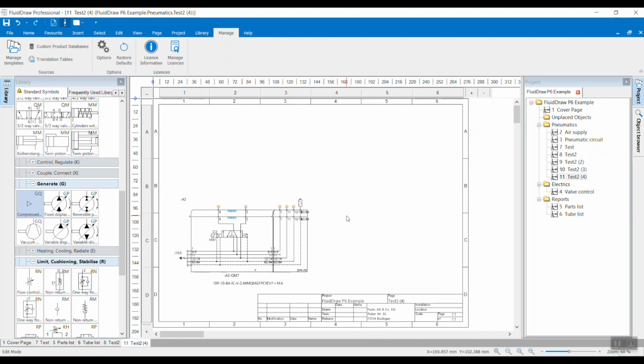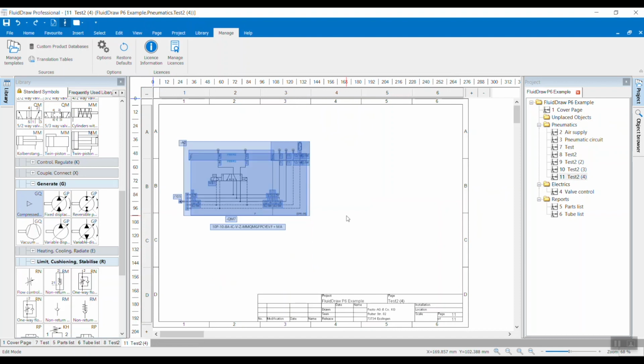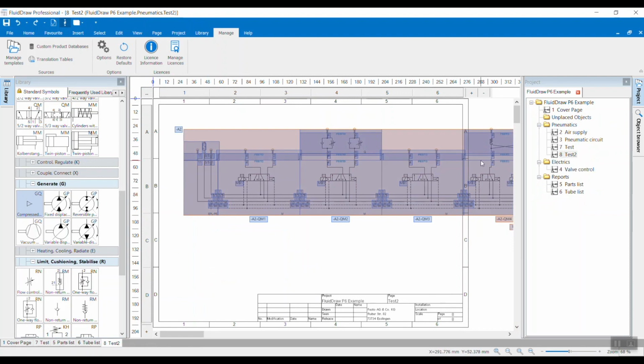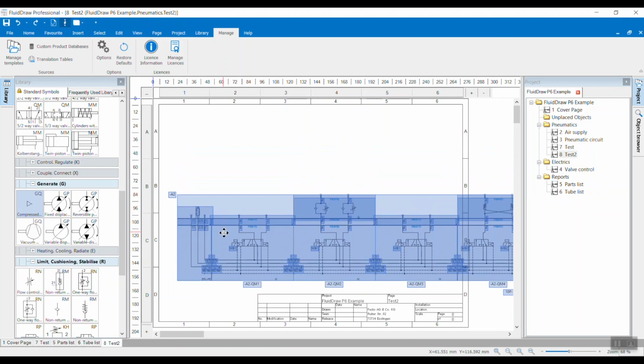To do this, all we have to do is go back to our insertion point before we broke the valve terminal across multiple pages, which is basically Control Z, as in any other application. Or you can click on the back arrow. It will also take you back. Now you see we're back to the insertion point. All I can do now is move the valve terminal, and here's my anchor point on the upper left-hand corner, and go through the same steps.